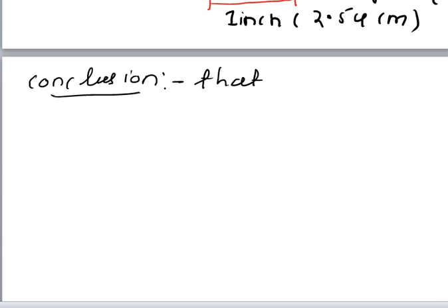Obviously it will be higher in case of lower sieve number, because in the same length there are only 6 square openings of equal size, and for 10 there are 10 square openings of equal size in the same length.